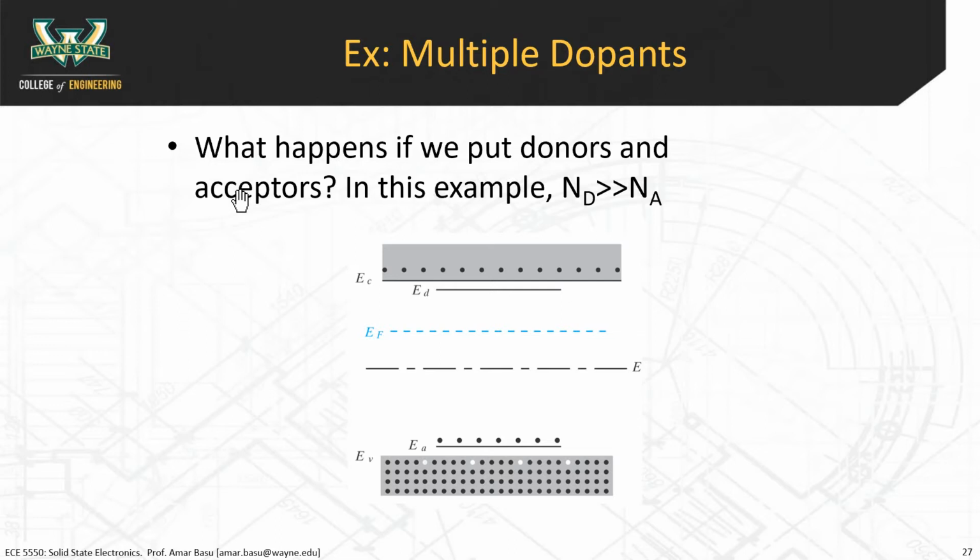Now, a couple caveats here, right? Obviously, if you doped it with arsenic and then you doped it with boron, you don't have the same material that you started off with. You still have these dopant ions, right? That can change the properties of the material also. But if we're just talking about carrier concentrations, then it's a way to, quote-unquote, erase.